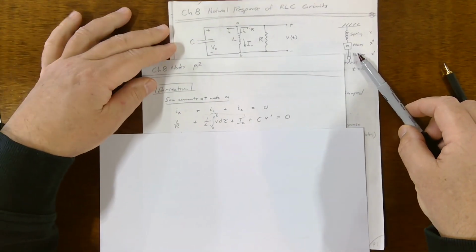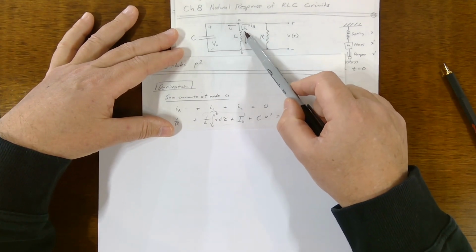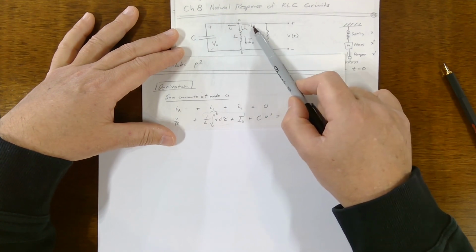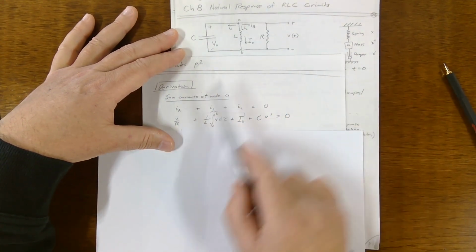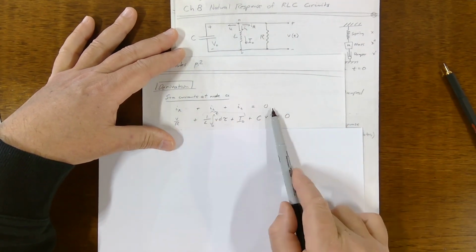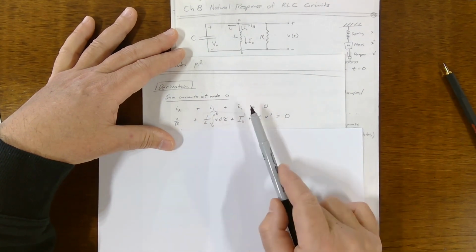which is similar to what I showed you for this mechanical system. So yeah, here, look, all these currents at node A are shown as leaving. Now, obviously, that's impossible. So at least one of these quantities will be negative. But we're assuming they're all leaving, so that makes them positive, just for the math. Once again, one of them will have a negative value in the solution. But anyway,